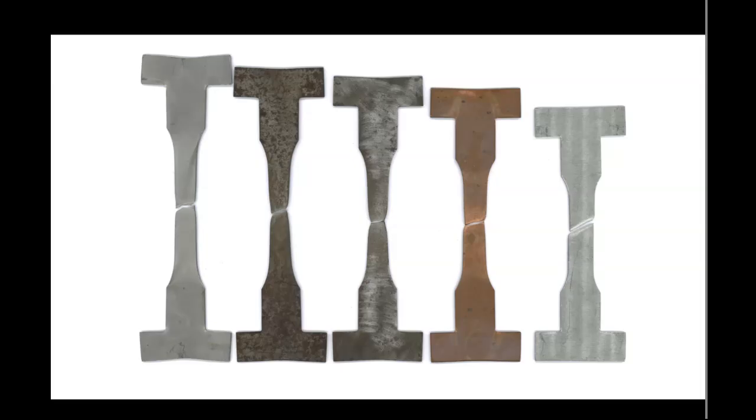fracture, slightly not at a normal angle, not flat or horizontal, but at a slanting angle. And then you see not a strong necking, but still defined thinning closer to the ends of the neck. You see a reduction of thickness, not within the shear lip area, but it's actually extending further into the bulk of the sample.